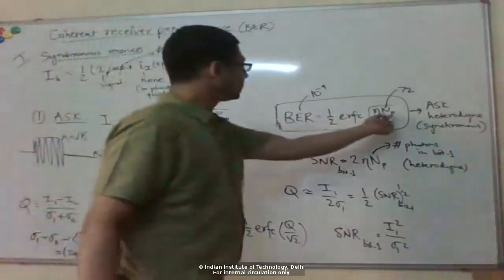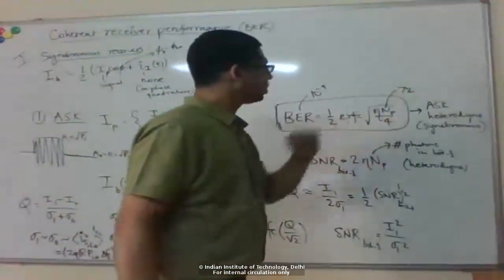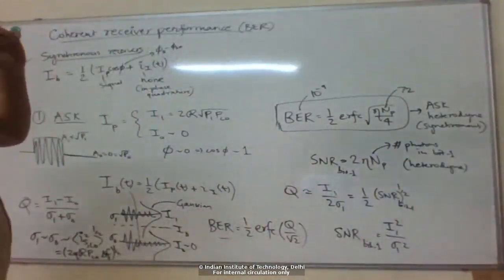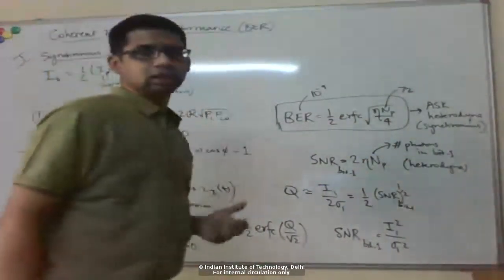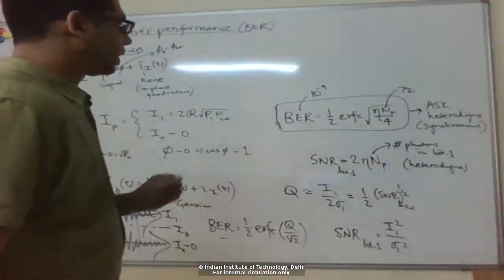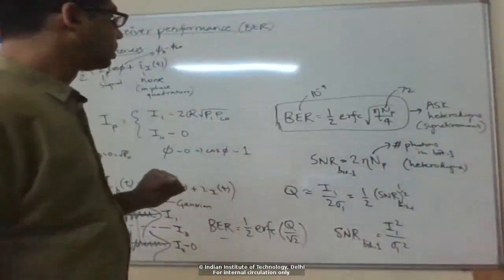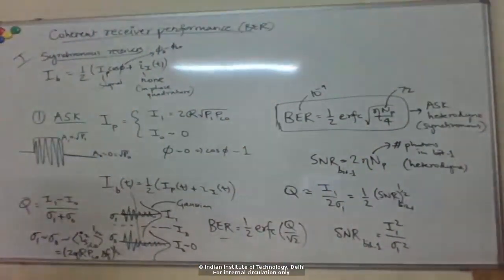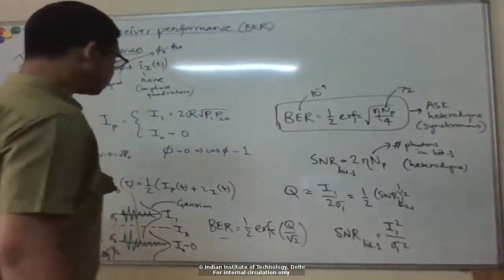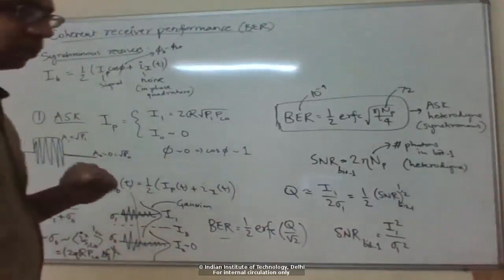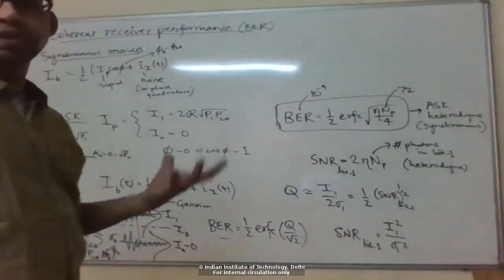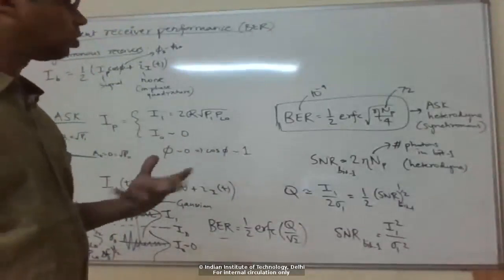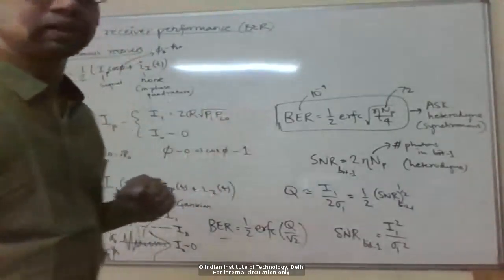Okay, so here we obtain a sensitivity of about 72 photons per bit. Compare that to operating in the thermal noise limit, about 1000 to 2000 photons per bit. With an optical preamplifier before the detector, we can improve the sensitivity down to maybe 200 photons per bit.